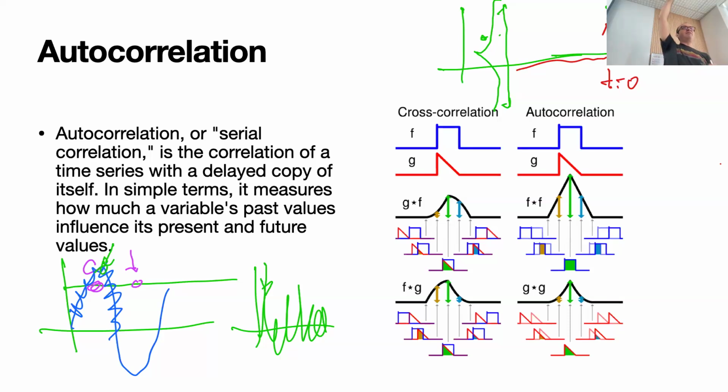So white noise has this Dirac function as its autocorrelation, and we don't have to generate it infinitely long. We can just generate noise, and its autocorrelation is a Dirac. If I do a Fourier transform of this, I get a flat spectrum. And this is the Wiener-Khinchin theorem. It says that I can generate a signal that has a flat spectrum.